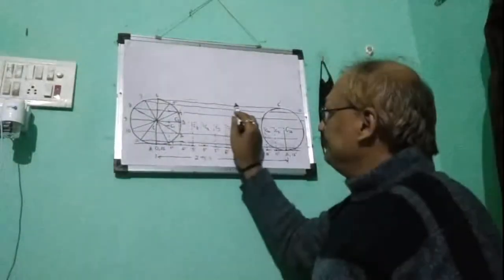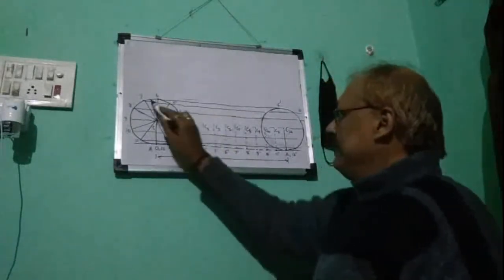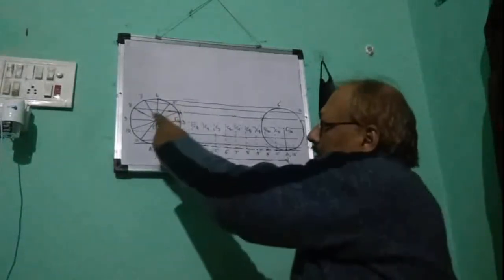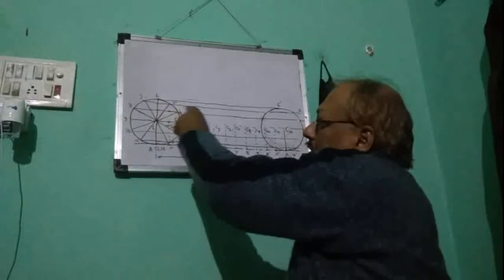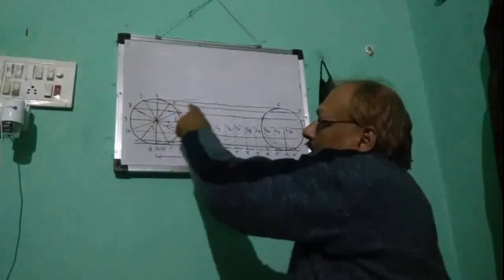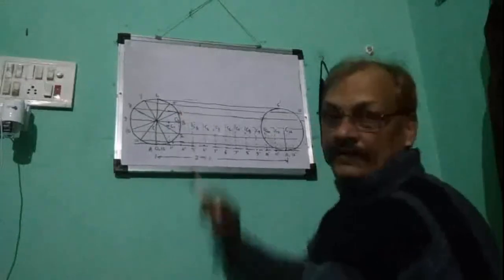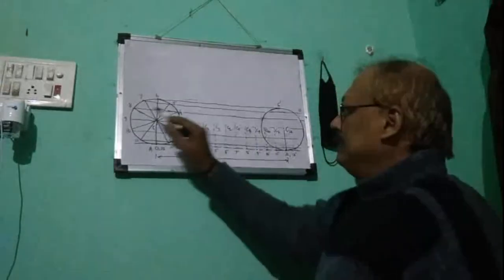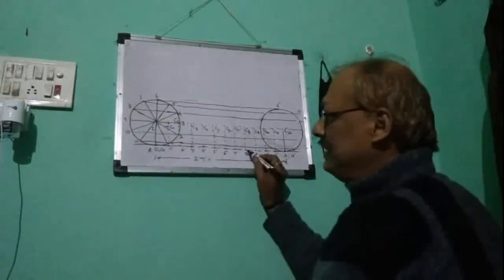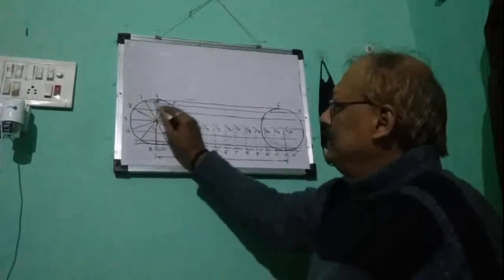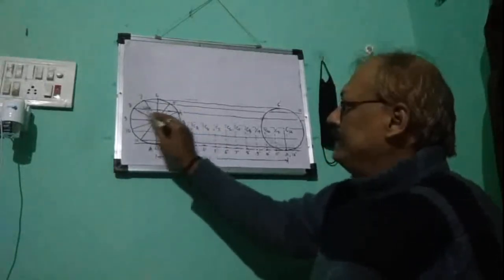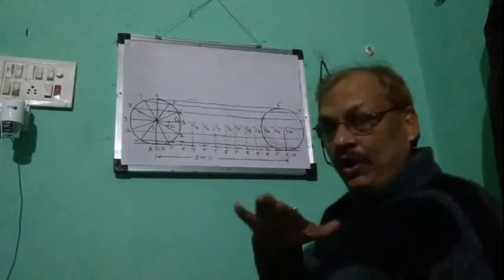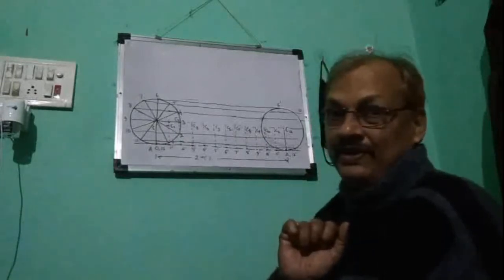Similarly, after that, when 7 will fall on 7 dash, look, it is going down. A will go down to the line through 7, which is the same line through 5, isn't it? And again, further, when 8 will fall on 8 dash, then A will reach the line through 8 or 4, both will be the same, isn't it? So like this we know on which horizon or on which line A will be.